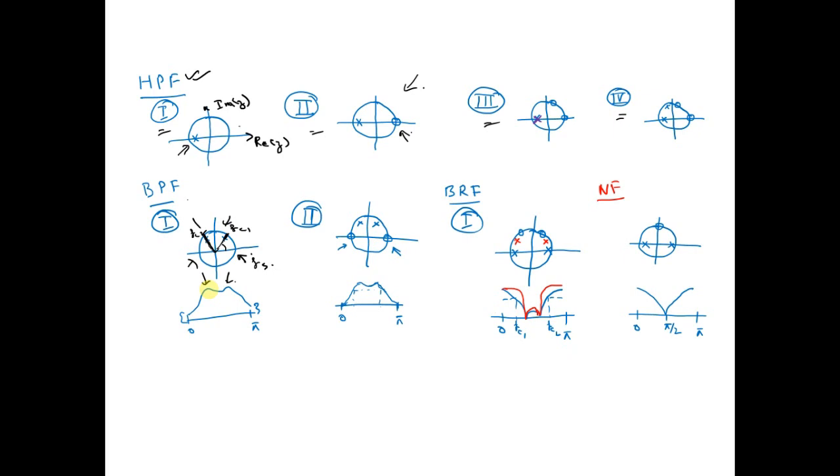Now this dip is nothing but the ripple, and then the amplitude decreases at both 0 and pi. Now there will be leakage of the frequency components, and due to that you will be having aliasing. To stop the aliasing, we can introduce 2 zeros at both the points.